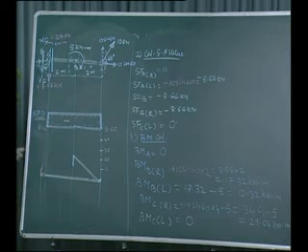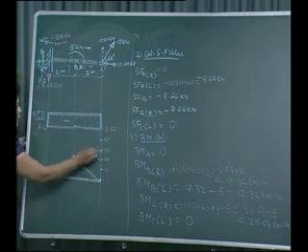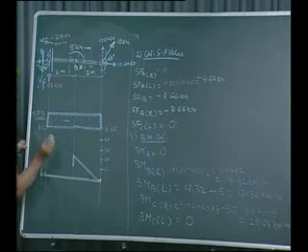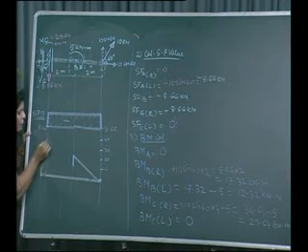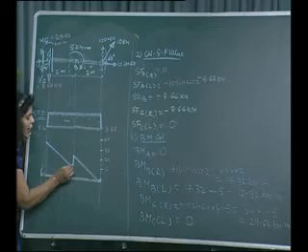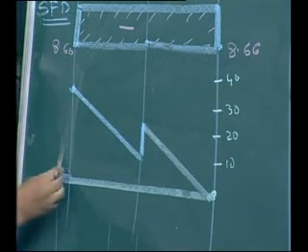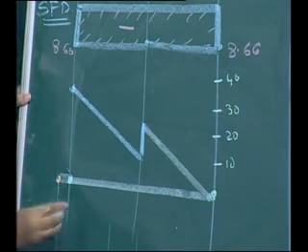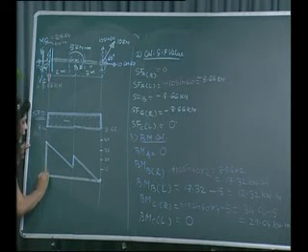Then bending moment at point C just right 29.64, approximately 30. What is acting between C and B? No load. It will be an inclined line. And bending moment at point C just left 0. So as it is a couple, it will be a vertical line.